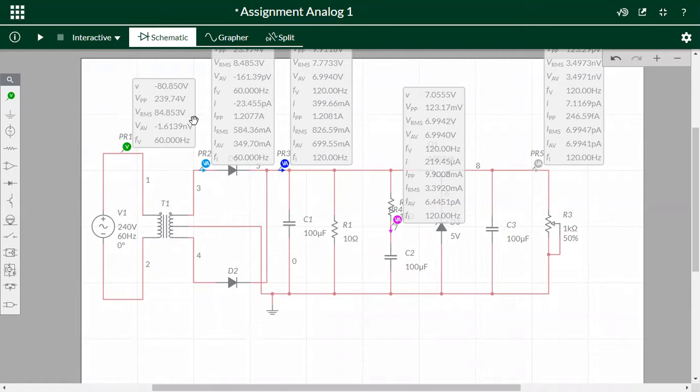As the name implies, this rectifier rectifies both the half cycles of the input AC signal, but the DC signal acquired at the output still has some ripple. To decrease this ripple at the output, this filter is used. In the full wave rectifier circuit using a capacitor filter, the capacitor is located across the RL load resistor.